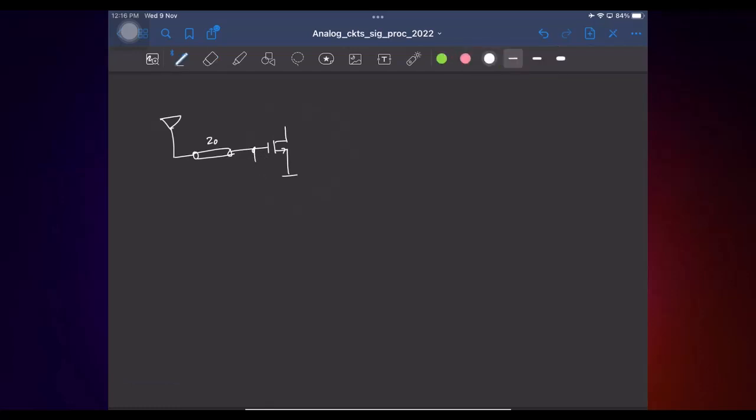Yeah, one brute force way is to put an R equal to Z0 here. At that frequency it should be very low, because the parallel combination of R and C should... Yeah, let's say this capacitor is small, right? I added the capacitor because you told infinity. Compared to infinity, the capacitor will offer something. Okay. So this is obviously one brute force way, but of course this is not preferred because the moment you add a resistor, yeah, noise, not gain, right?